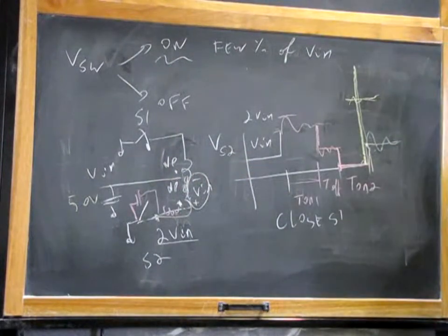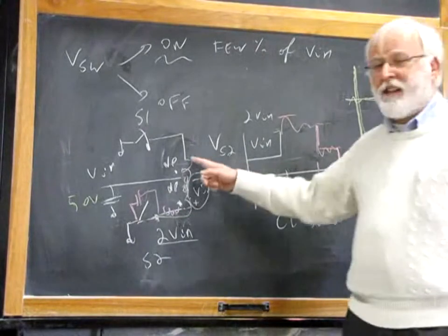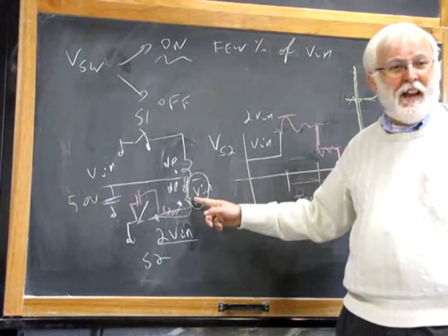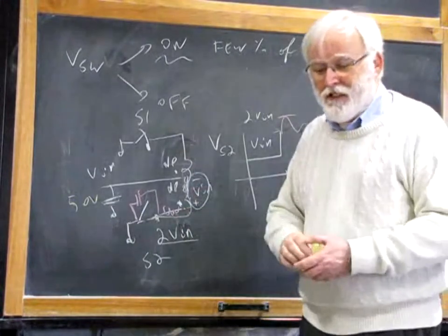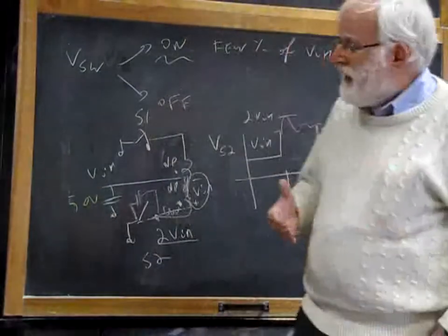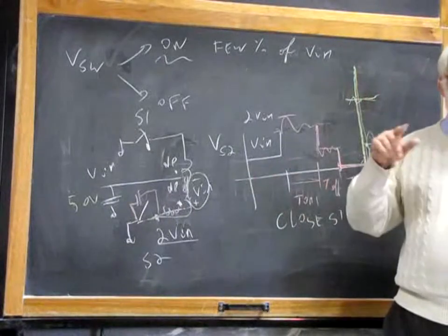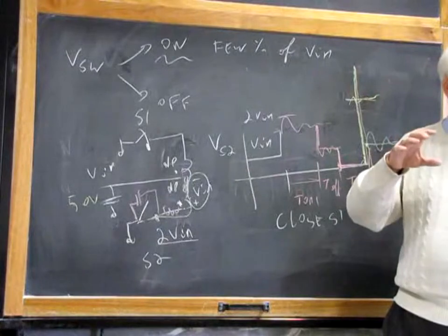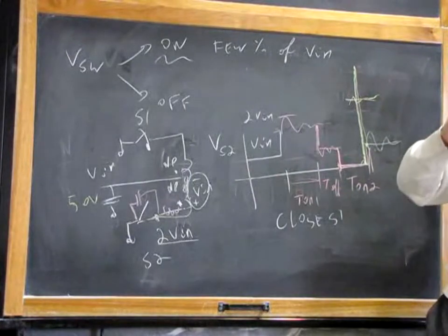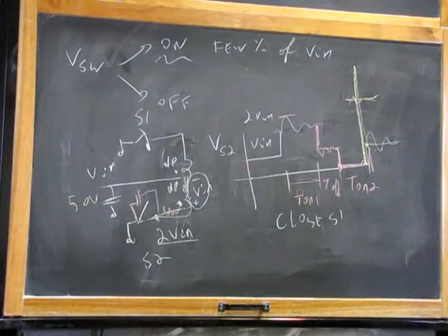But in order to design the snubbers, could be just a Zener, could be a more complicated snubber, you need to know the parasitic elements of this transformer. And you don't know these parasitic elements unless you have the transformer in your hand, unless you have mounted the circuit. So my idea was, I hope you understand that you have to start with low voltage, low power, measure the ringing, measure the spikes, evaluate them, and then put the snubbers and go up in power. Well, my message was not understood like this.